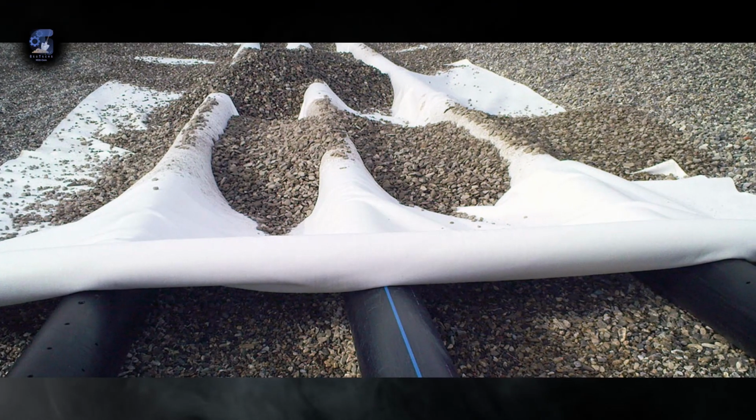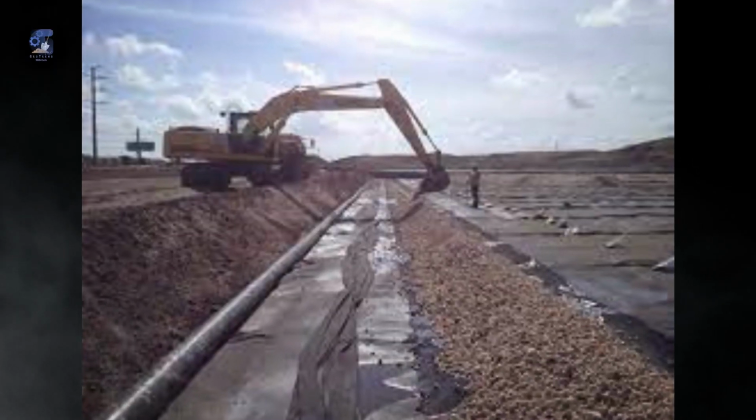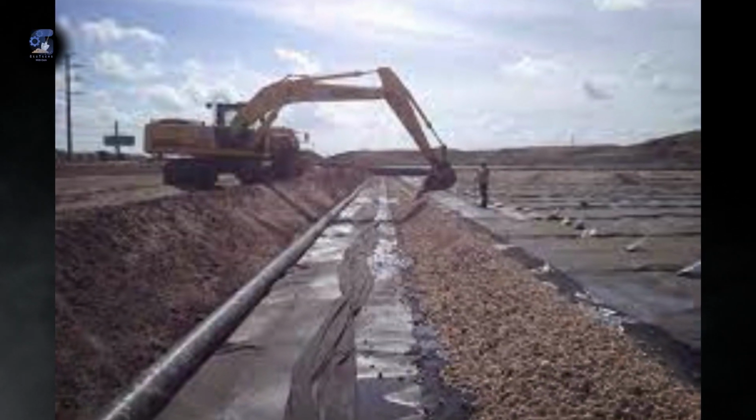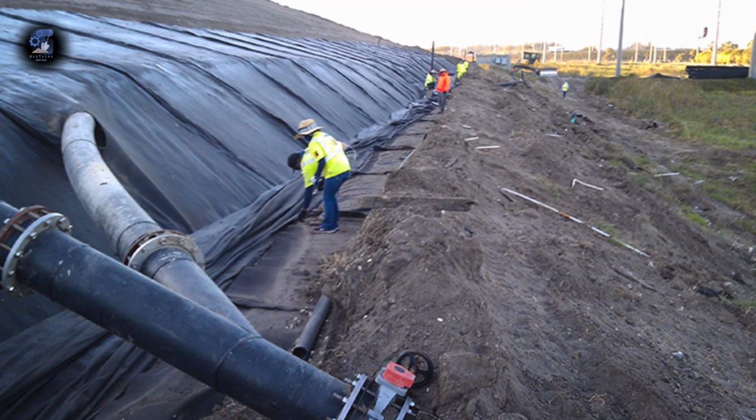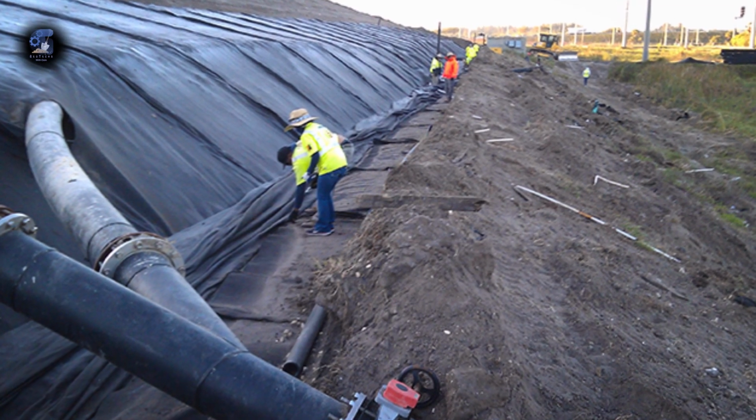The leachate collection pipes are also placed at regular intervals across the landfill base with an adequate connection to the geocomposite drainage layer. The combination of pipes and geocomposite drainage layer provides high volume flow paths for the leachate, which reduces the pore pressure and increases the stability of the landfill.